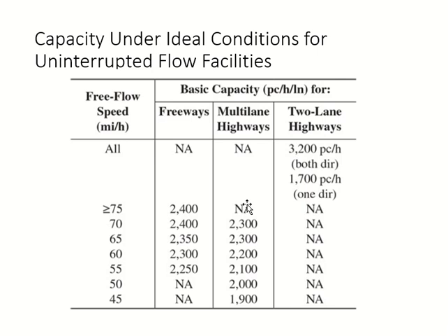Okay, so why not 1,700 for both directions, a total of 3,400? The reason is, on two-lane highways, these two directions are very close to each other, and in many cases, without any separation or median, people from one direction may go into the other direction to overtake someone. So one direction has an effect on the other. This effect restricts the other direction, so both of them cannot achieve the same value. When one reaches 1,700, the other one cannot reach the same value because of the effect of the direction which has already reached 1,700. So that's why we have a deficiency here in the total.